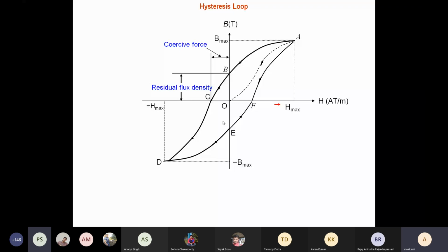Sir, to stop the hysteresis loop completely? Yes. Sir, we have to apply this cycle of magnetism and demagnetism with an AC supply with decreasing amplitude. Sir, it would then reduce to 0. Yeah, so you have to check what actually happens, because the magnetic characteristics are also not entirely understood. Okay, Sir, I will.